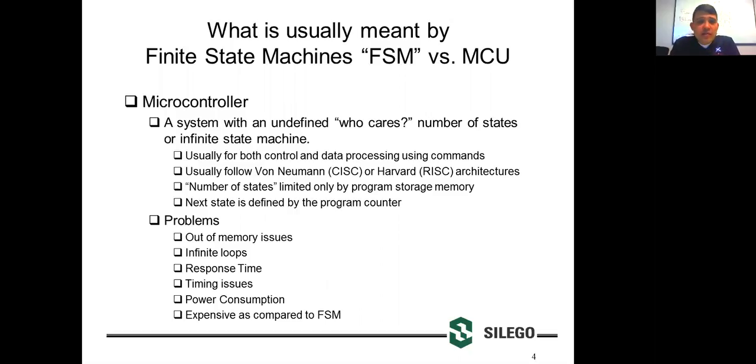And naturally, because these are clock systems, you never get rid of power consumption. Now, microcontroller companies have done an amazing job to reduce the amount of power and use all kinds of sleep and hibernate modes and various ways of turning on and off PLLs and clocks to really get the amount of power consumption wrung out. But nonetheless, microcontroller architecture is not the most efficient architecture for power consumption when you're trying to do relatively simple problems. And then finally, they're expensive compared to finite state machines or asynchronous state machines for doing simpler control type applications.